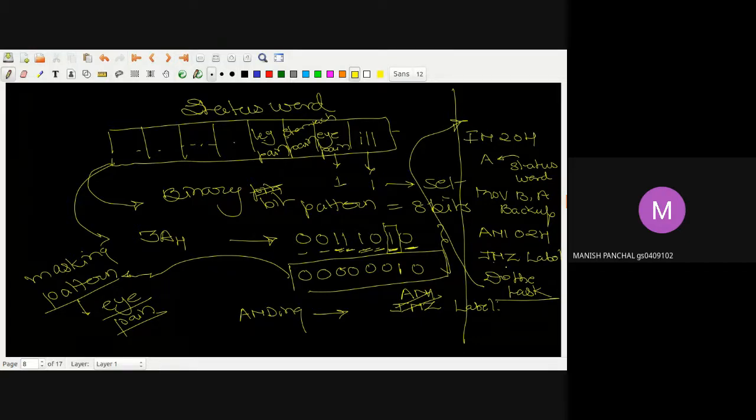यहाँ पर जो इंस्ट्रक्शन है वो ऐसा है कि यहाँ पर ये मान लो, is it 0. ओके, मतलब सारी की सारी जो बिट पैटर्न थी वो अगर मान लो यहाँ पे दो कंडीशन हैं, क्योंकि यहाँ पे JNZ यूज कर रहे हो ना, तो या तो 0 फ्लैग सेट होगा या नहीं होगा. अगर 0 फ्लैग सेट नहीं है, इसका मतलब ये होता है JNZ. If the 0 flag is not set, then jump to label location. If the 0 flag is set, then perform this task. So the task will be performed when the 0 flag is set.